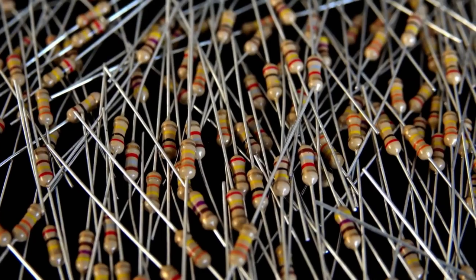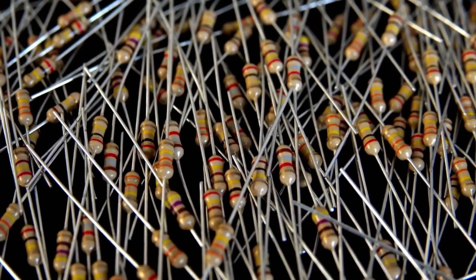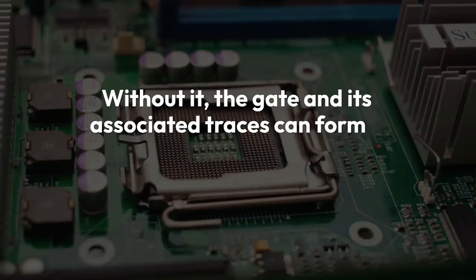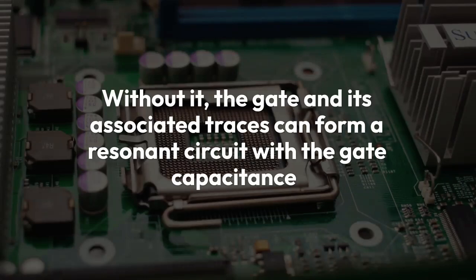Finally, the gate resistor helps prevent unwanted oscillations or ringing on the gate. Without it, the gate and its associated traces can form a resonant circuit with the gate capacitance, leading to destructive ringing that can cause false triggering or even damage the device.